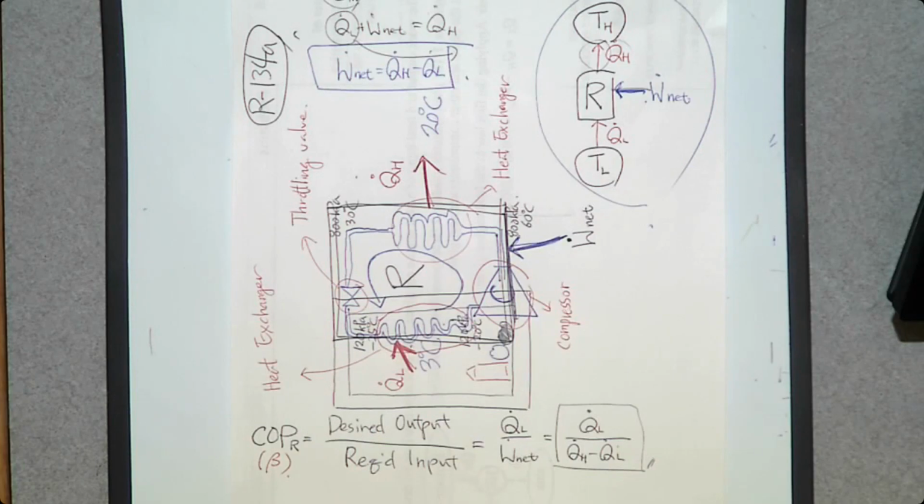Once you are able to determine what it is, you should be able to come up with the schematic diagram, and then how you evaluate the performance of the system, either by efficiency for a heat engine or COP for a refrigerator. And one last thing is going to be the energy balance equation. That's all you need to do.